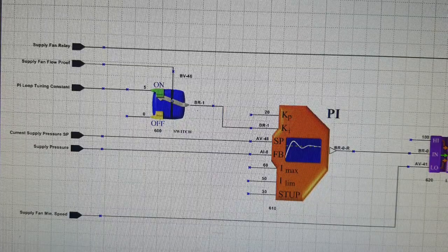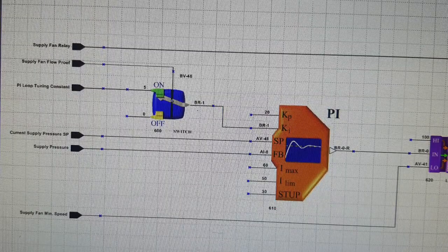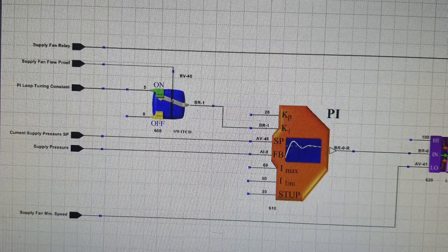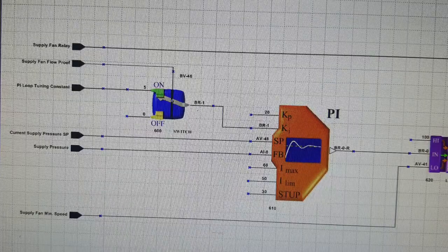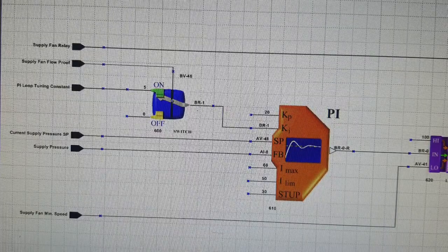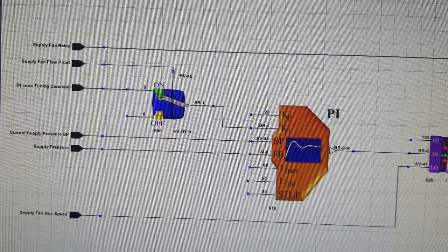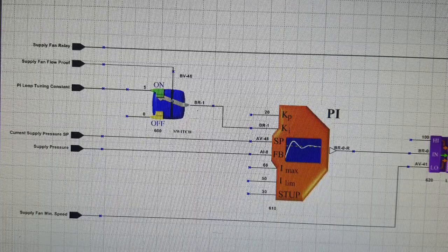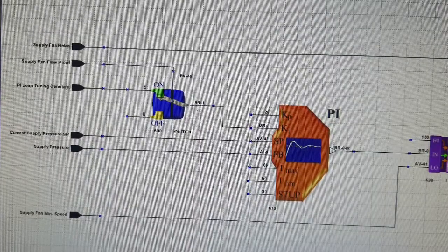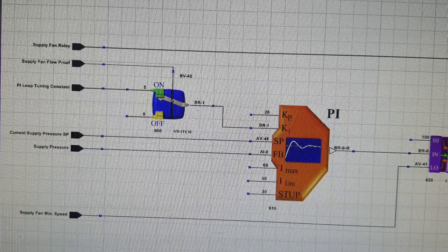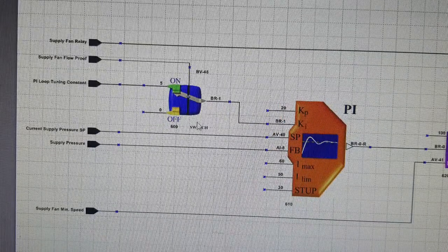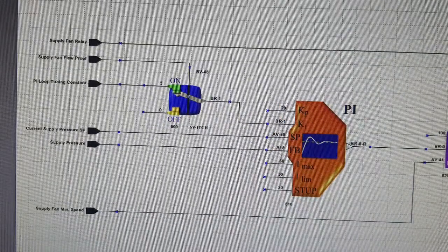And in countries like the US, we use current sensors also, where the current sensor input tells us there is power going to the fan load side, so that means the fan is operational. So based on these conditions, our fan is ready to go.